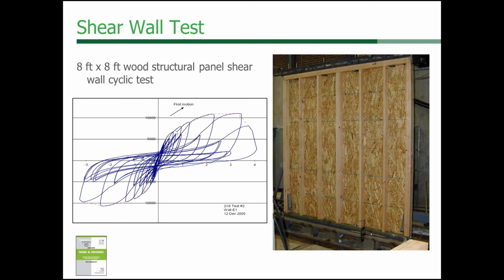And what we see here is along the lines of 1.5 inches, where we have about over 10,000 right now. Around this location is where we actually design our shear walls, the strength that we design our shear walls to. So it's 3 times less strength, and 3 times less drift, around 1 inch. That's where we design.